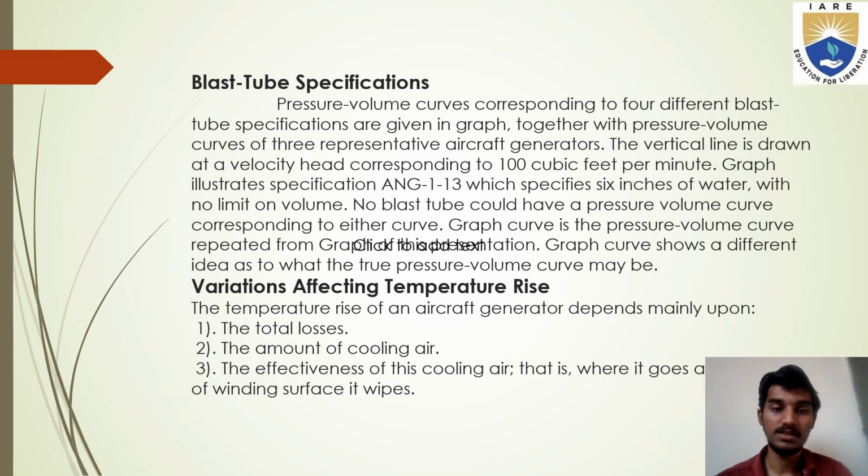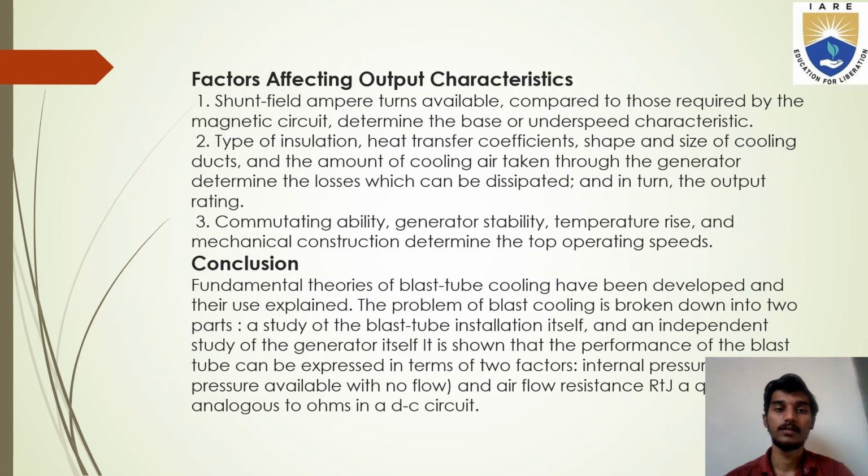Variations affecting temperature rise. The temperature rise of an aircraft generator depends mainly upon the total loss, the amount of cooling air, the effectiveness of this cooling air, that is, where it goes, and the area of heating surface it wipes.